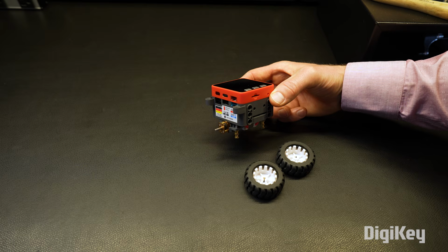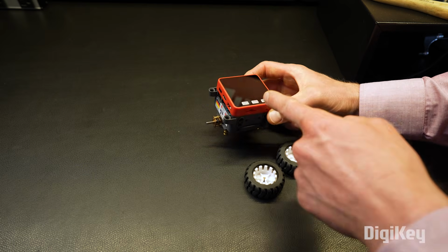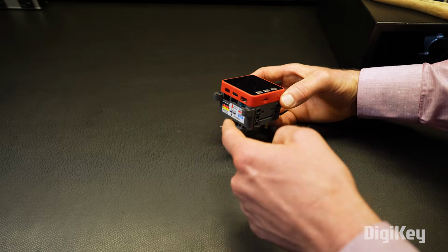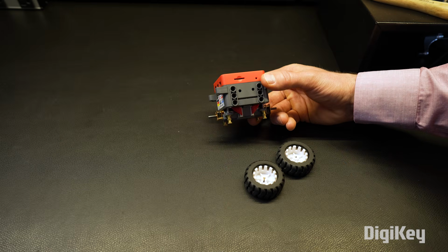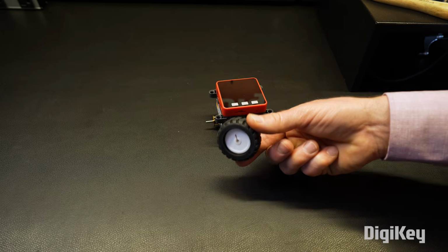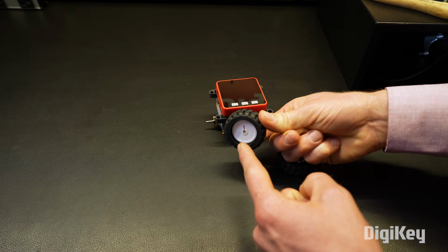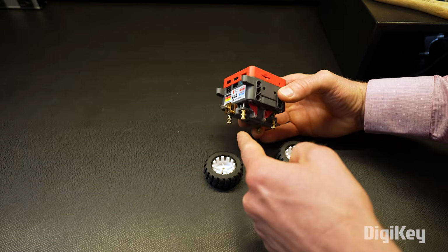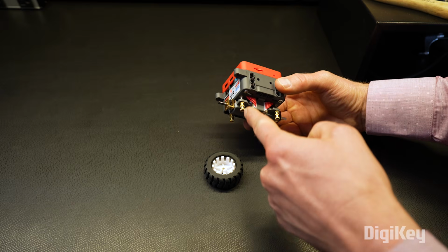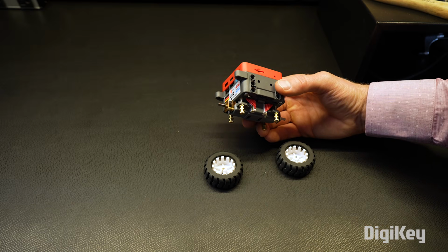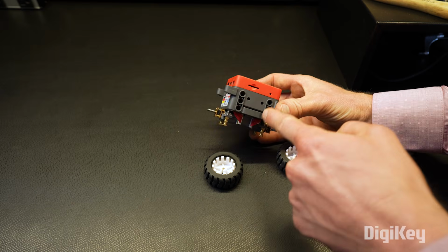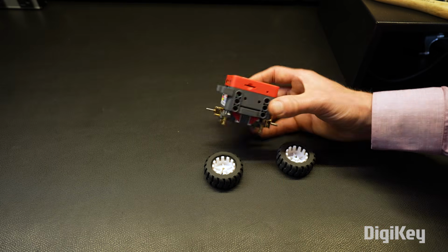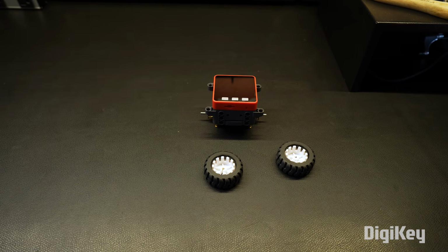If a part is of uniform density, then we can assume the center of mass is in the same place as the geometric center, or centroid. We can assume our wheels are uniform enough to estimate that the center of mass is right in the middle. The chassis, however, is made up of a combination of plastic, metal, and electronics. The motors and batteries are the densest pieces, and they're located at the bottom. As a result, the center of mass is likely lower than the centroid for the chassis.